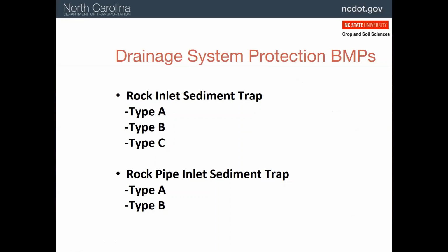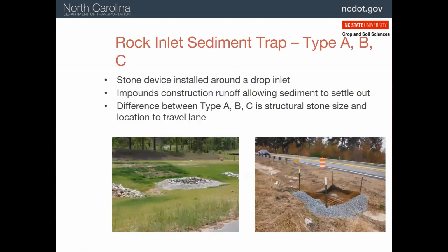All right, well, at some point on most projects, a storm drain system gets installed. This means culverts under the roadway and pipes, etc. We don't want any of these to become clogged with mud. So there are a number of practices we're going to use to prevent that. So drop inlets will eventually be at ground level and drain roadway runoff through a grassed or lined drainage ditch. There are 3 types of inlet protection that we're going to use, depending on location and the expected runoff volume.